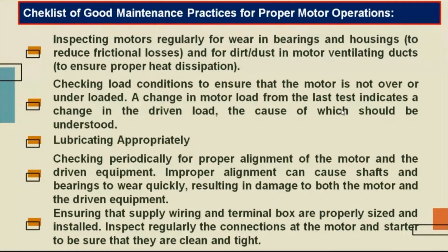At the same time, a change in motor load from the last test indicates a change in the driven load, the cause of which should be understood. So the skilled personnel employed on the shop floor, who are actually working on the motor, should monitor the change in the motor load from the last test, whenever it is done, and the proper cause of it should be understood. That is, they should know why there is a change in load, and if they can reduce these changes, that would be better.